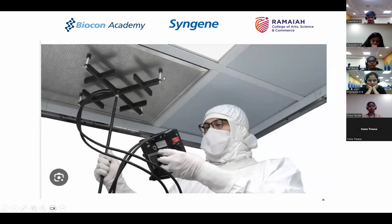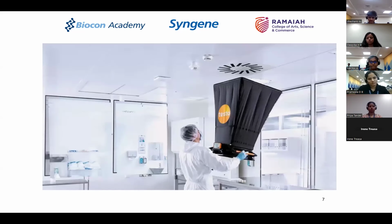To get accurate values, there is a particular distance, around 1 inch or 2 inches from the grill. The values drawn from this are taken at 5 different portions of this particular HEPA filter, and they will average it out. They will take the room balancing air volumes.